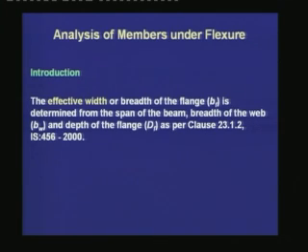Another important consideration is to calculate the breadth of the flange or the effective width of the flange. If it is an isolated beam with a small width of the flange, then the full width of the flange can be considered as the breadth of the flange. But if the flange is a part of a slab, then we have to calculate an effective width from the slab, where the assumption is that the compressive stress is uniform over the effective width.